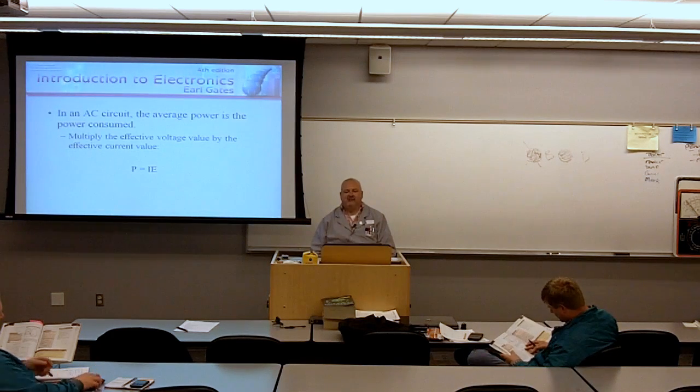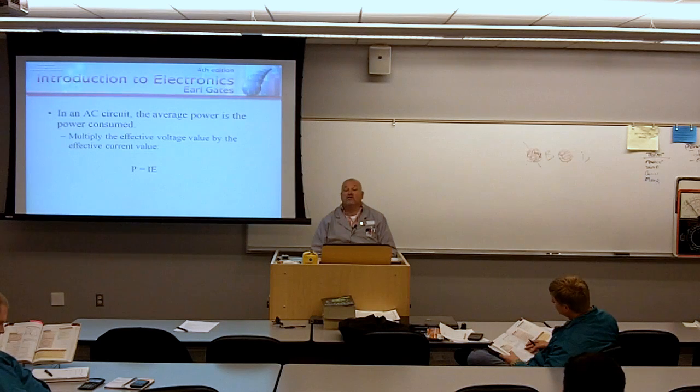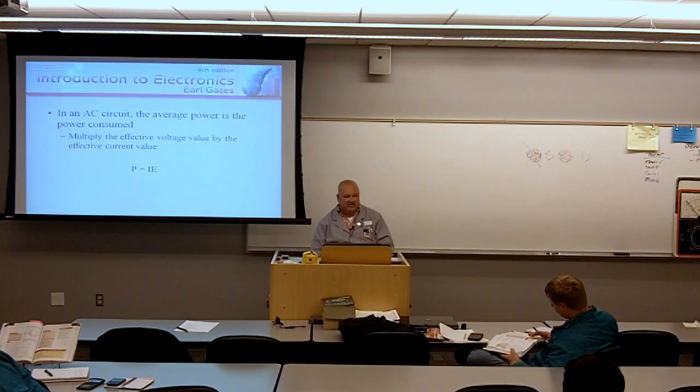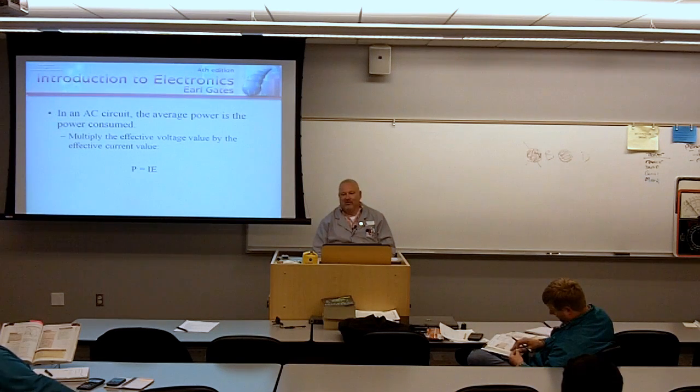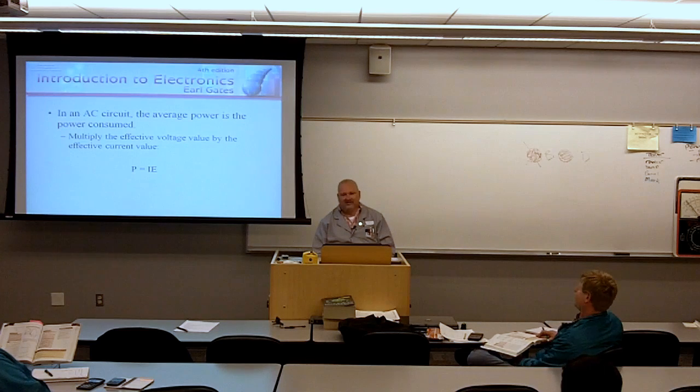In an AC circuit, the average power is the power consumed. We multiply the effective voltage value by the effective current value. So it's that effective value, that RMS value. Sometimes you see the audio manufacturers playing around with that: 1,000 watts peak. Since your speaker is basically a resistive load, it's really going to be only the effective value that gets out, but it allows them to put 14.7 gigawatts on the box or whatever as a marketing ploy.